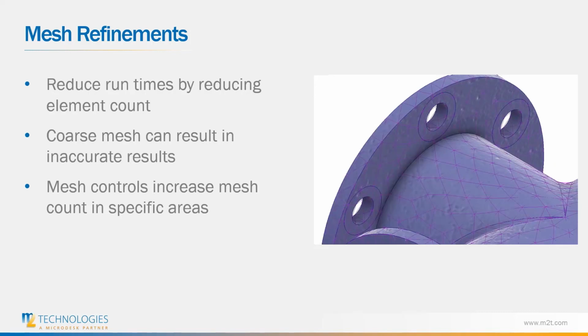Once you apply it, you'll get a general mesh. You can see in the bolt holes and along some of the surfaces where the mesh is creating linearizations across rounded surfaces. In the large radii, this shouldn't be a problem, but can cause more of an issue where we have the smaller radii. What we can do to fix this is we can come in and add mesh controls to define a finer mesh around those areas.